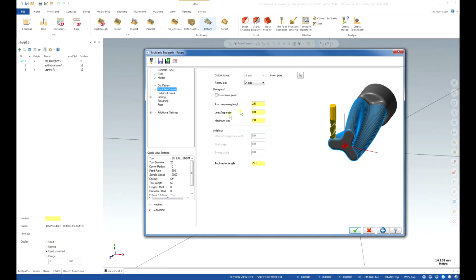Even if you use the center of the rotation as your control point, you will still output y-axis motion, y-axis movement. We switch off this option as we want our cuts to be normal to surfaces. Your maximum step over you set here, maximum step. So this is the distance between two passes. We're going to use 7mm for our roughing up.